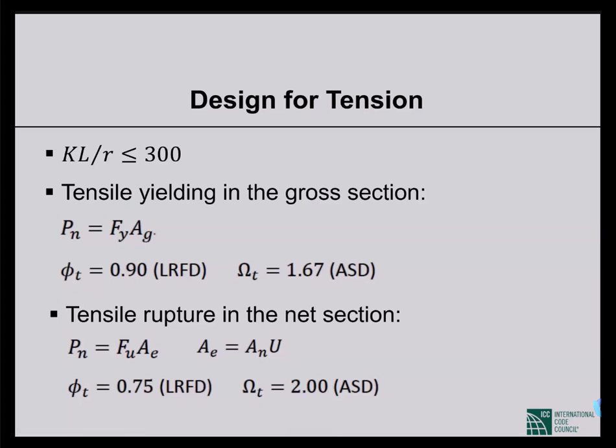Why do you need this factor? We'll see. Now, An is, for example, if two members are bolted together and one of the members acts as a tension member, at the location of the bolting there are holes, right? If we subtract the cross-sectional areas of those holes, then we'll get the net area. There are rules for that, how much we have to subtract, etc. I'm not going into the detail on those, but we can calculate the net area, but we have to multiply it with one factor that is called the shear lag factor. Why do we need the shear lag factor?